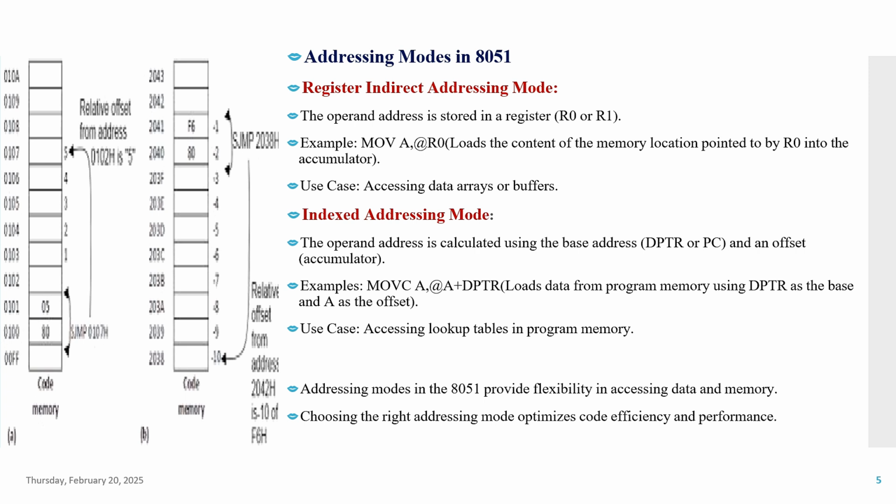Addressing mode of 8051. To understand addressing modes, we have to determine how the microcontroller accesses data and instructions. Efficient data access is crucial for optimizing performance in embedded systems. The 8051 microcontroller supports several addressing modes, each with unique characteristics. Clear? Types of addressing modes: immediate addressing mode, register addressing mode, and direct addressing mode.